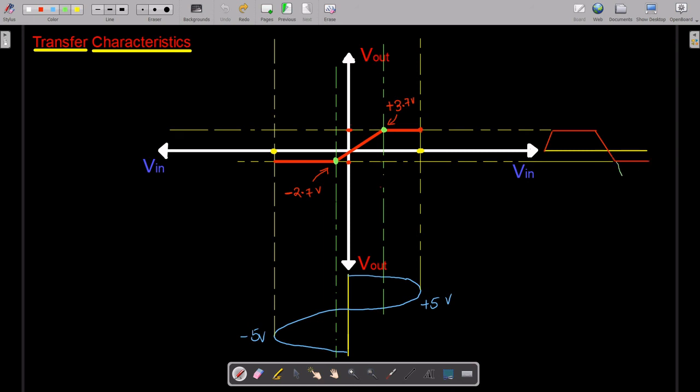Let's suppose it is not getting clipped, and it would be something like this. That means your negative side is not clipped and it is getting reflected as it is. So what you can do, you can draw this line over here, and then extend this particular line over here, indicating that the slope is constant. Okay, but since your negative side is getting clipped, your slope automatically becomes 0, and this is how it is indicated in the transfer characteristic.